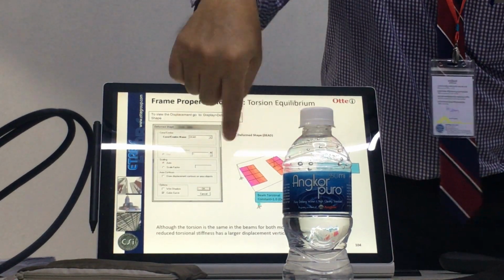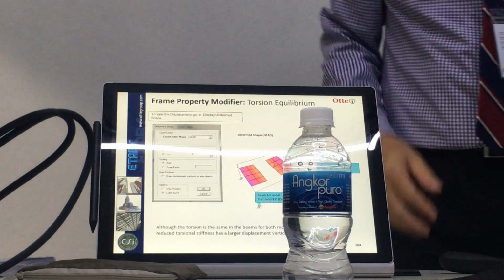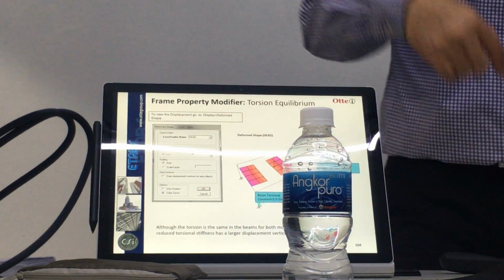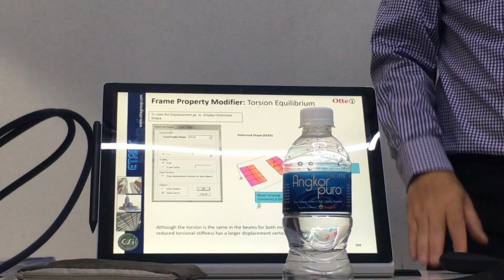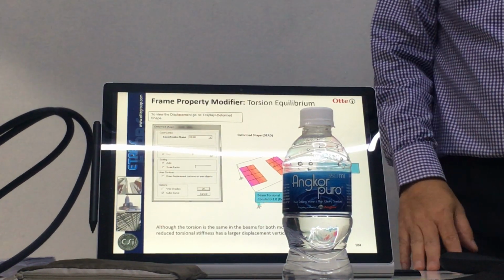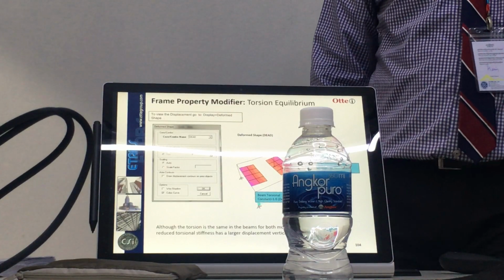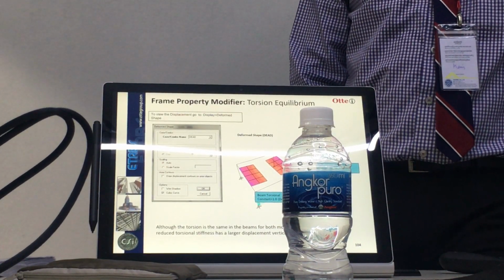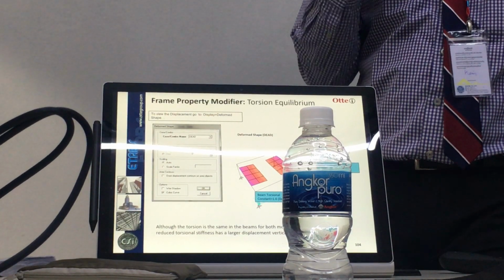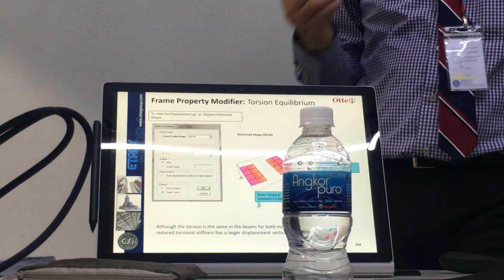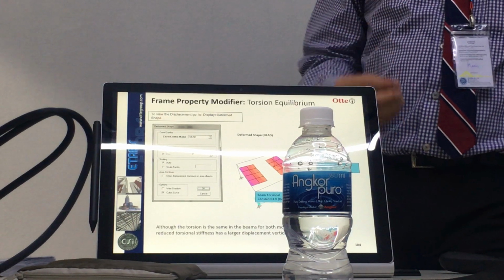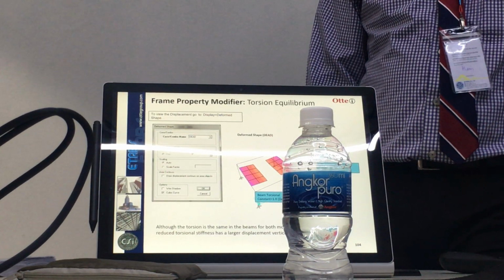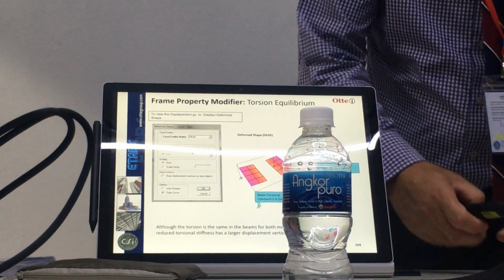This beam, these two cantilevers left, the fixity is the torsional stiffness of the beam. So both of them have different stiffness in the joint, in the fixed joint. So it has different notation. So your calculation is not correct because you don't account for the flexibility in the support. So that is another concept you need to know. Sometimes we always trust our own calculation, but your calculation may not simulate the actual behavior because you have a simplified approach. Yeah, all right. So that is something to know about.